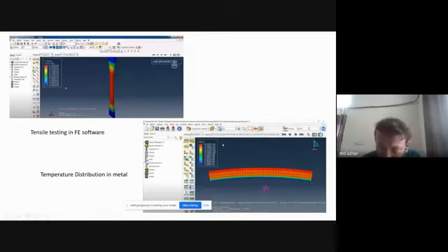It's showing NT11. So what is the range of the temperature? You can see it's 2.5 into 10 to the power 1. So basically it has just started, so the heating has not yet taken place. It's kind of at room temperature. But once the heating takes place, the temperature will keep on increasing, and you can see which location has high temperature and which location has low.